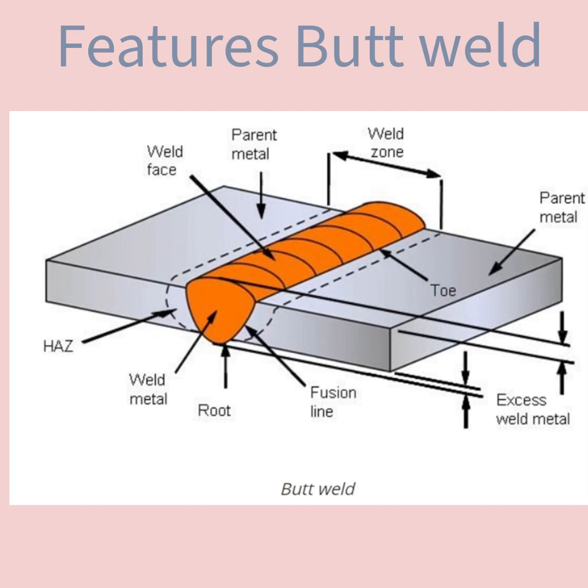Third is weld metal, which is all metal melted during the making of a weld and retained in the weld. Another very important term is heat affected zone or HAZ, the part of the parent metal metallurgically affected by the heat of welding or thermal cutting but not melted. Fusion line is the boundary between the weld metal and the HAZ in a fusion weld. Weld zone is a zone containing the weld metal and the HAZ.